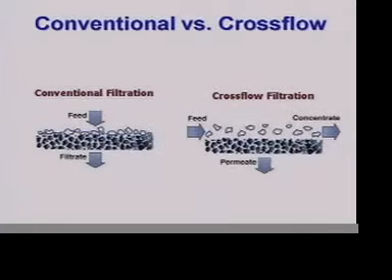The 100% of what you want to treat in the way of a contaminated water supply flows through this medium, whatever it is, and hopefully everything you want to remove is left behind on the surface. It's a batch process. Once this gets so full of whatever you're trying to remove, you have to take the system offline and regenerate it, or throw it away if it's a cartridge or something like that. But it's treated as a batch process.